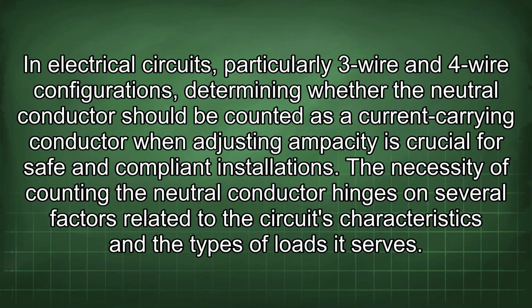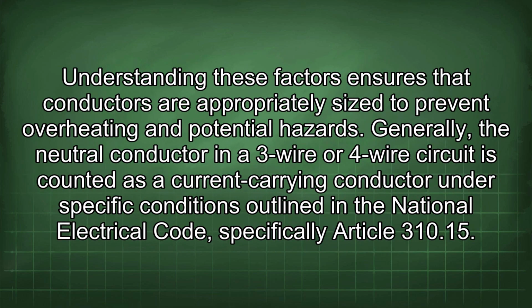In electrical circuits, particularly 3-wire and 4-wire configurations, determining whether the neutral conductor should be counted as a current-carrying conductor when adjusting ampacity is crucial for safe and compliant installations. The necessity of counting the neutral conductor hinges on several factors related to the circuit's characteristics and the types of loads it serves. Understanding these factors ensures that conductors are appropriately sized to prevent overheating and potential hazards.